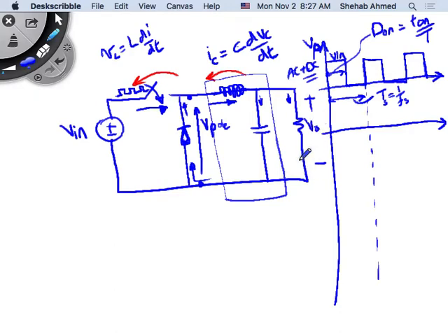That's my goal, right? So now, what do the waveforms across all of these components look like? I have to design my capacitors and inductors to make sure that the capacitor, for example, has enough charge to maintain the voltage across the load when it's not being recharged, right? That's how you design the capacitor.